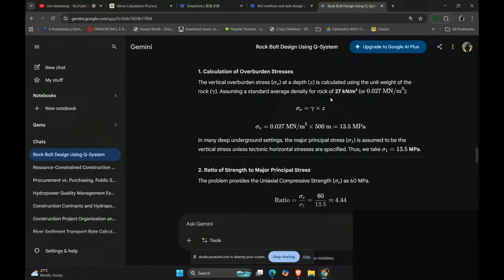It does not require any value of Q' with the excavation dimensions of 2.5, 4.5 or 6.25. For category 5, 2.5 by 1, it requires rock bolts at 2 meter spacing with a 20 cm thick layer of steel fiber reinforced shotcrete.